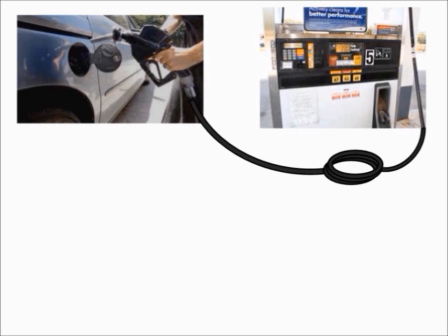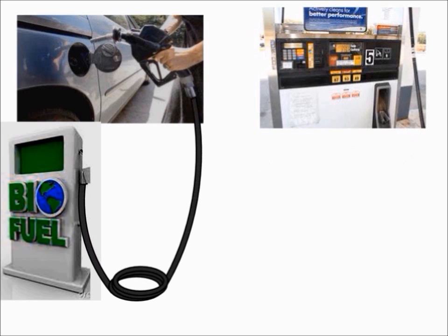As you may be aware, some cars today run on flex fuel or E85, which means it uses a mixture of ethanol and traditional gas. However, ethanol doesn't contain as much energy as gas per volume and cannot be used at high concentrations or it could cause traditional engines to fail. Butanol has similar energy density to gasoline and can be used in current combustion engines without modification.